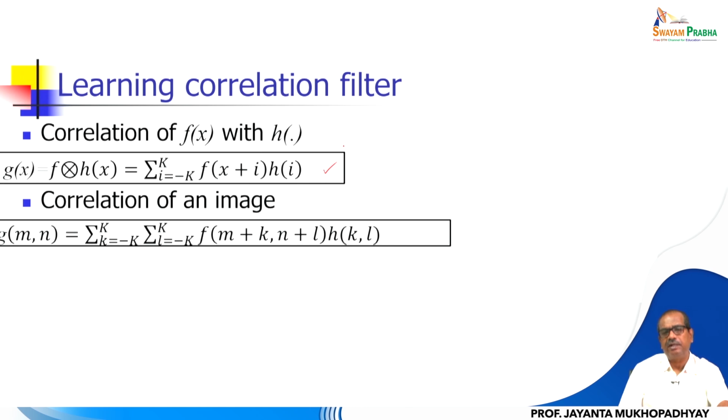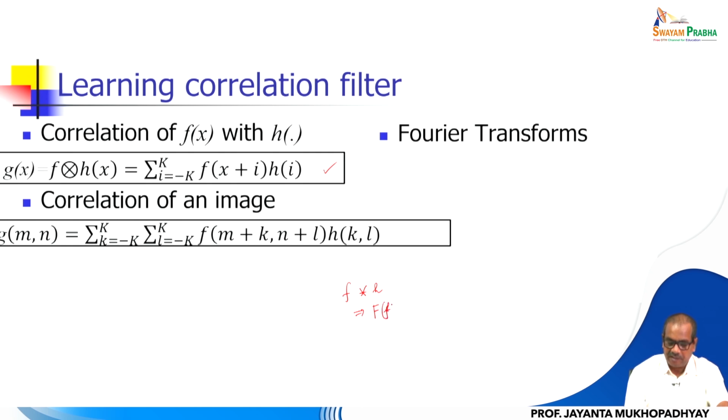So the relationship in the Fourier domain is also quite similar. Convolution, we know, becomes a multiplication operation. Say you have the filter f, and I perform the convolution operation with h. We know that the Fourier transform of f, let me denote it as F, and the Fourier transform of h is H. So you just multiply them, and what you get is the Fourier transform of their output. So if y equals f star h, you get F of y in this case.